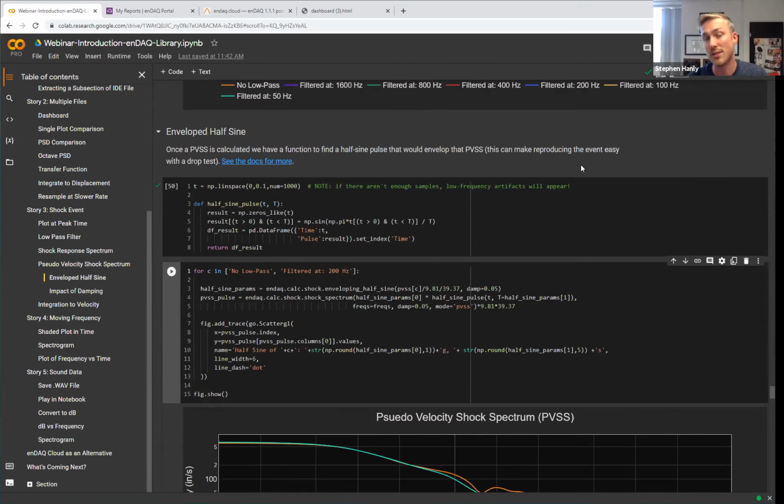I compare acceleration data from an earthquake to a gunshot. The earthquake has really low amplitude data, but that's a lot of energy that can really break buildings and tear apart various systems. But if you only looked at that time domain data, you'd say there's no damage potential in this data set. That's just not true. You need to take into account the frequency content too.